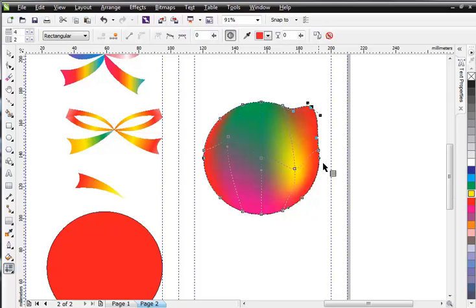We can also change the shape of the base figure. Although it's possible, it's best if we create a base figure before applying a mesh effect to it. We can also move the whole section. Remember that when we do that, all points will be moved simultaneously. Press Ctrl and Z. Clicking twice adds a new point. You can also just move the line segments. All these actions will modify the gradient effect. So this is how we can create a nice gradient effect with the Mesh tool.